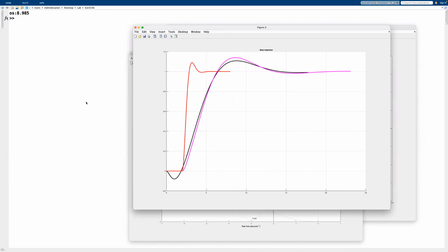There we go. Now, of course, it will go like 20 seconds, but you can see that there's a huge difference. It doesn't have to be, but in our case, it is quite different. The reason is that we didn't optimize the Padé approximation versions of the PI controller, and I just got rid of basically a pole and then directly used the structure's advantage.